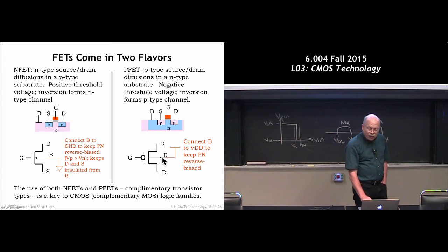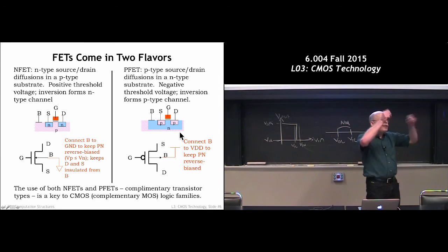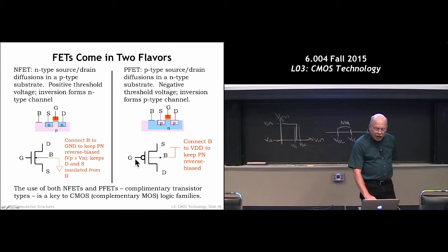We actually have a different type of voltage-controlled switch called a P-channel MOSFET, where we've just flipped all the different types of the semiconductor materials around. This switch is on when VGS is below the threshold. So typically for a particular value of VGS, one of these switches will be on and the other will be off.